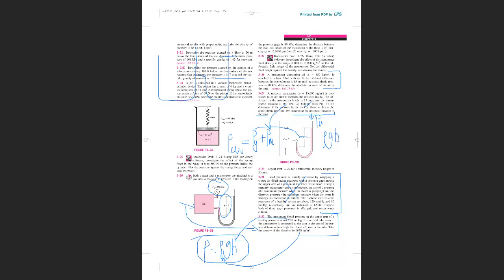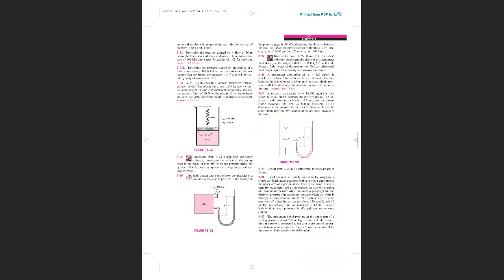So from here, there is one thing I made slightly incorrect. Millimeter Hg means P is equal to rho g h, where rho is rho mercury, right? Then h is equal to P over rho g. Yes, you have the density. So it is exactly like this problem. Please have a look at it carefully and try to solve it.